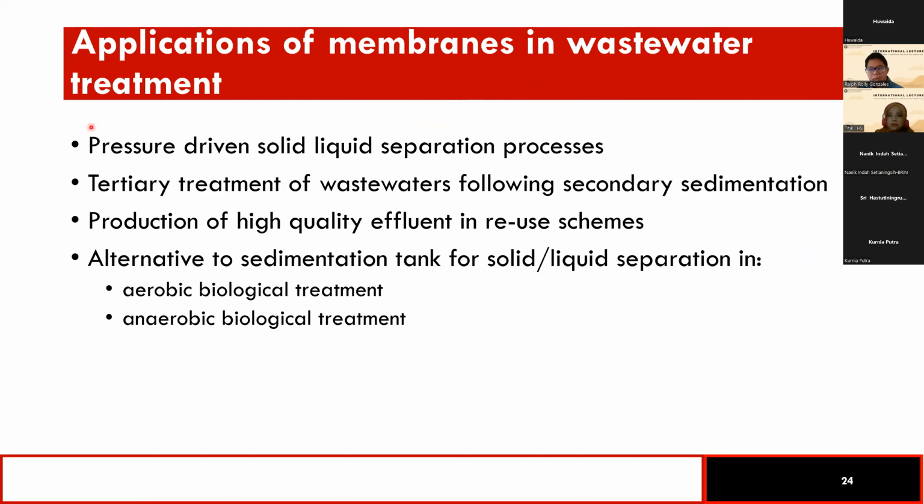So this is MF to remove the bacteria and large solids, UF to remove the colloids and the larger size molecules, NF to remove the sugars and the salts, and RO or FO. RO is pressure driven. This removes most of the salt, and we are left with fresh, usable water.